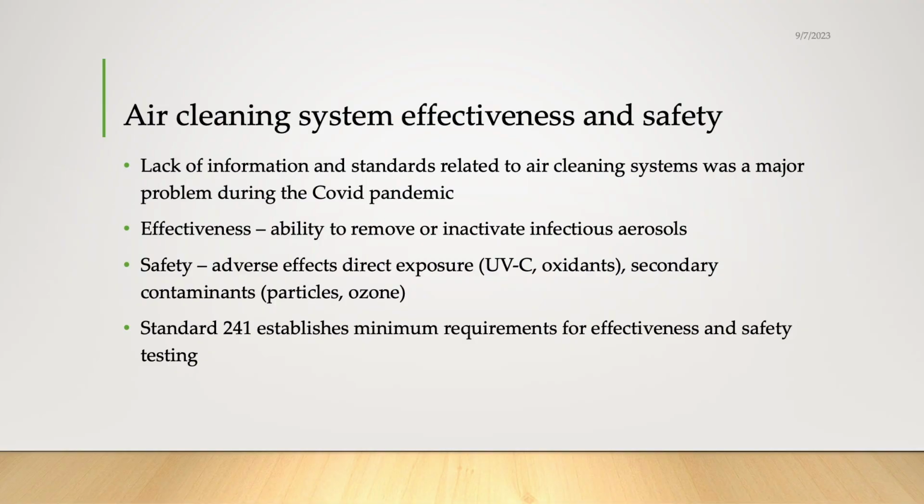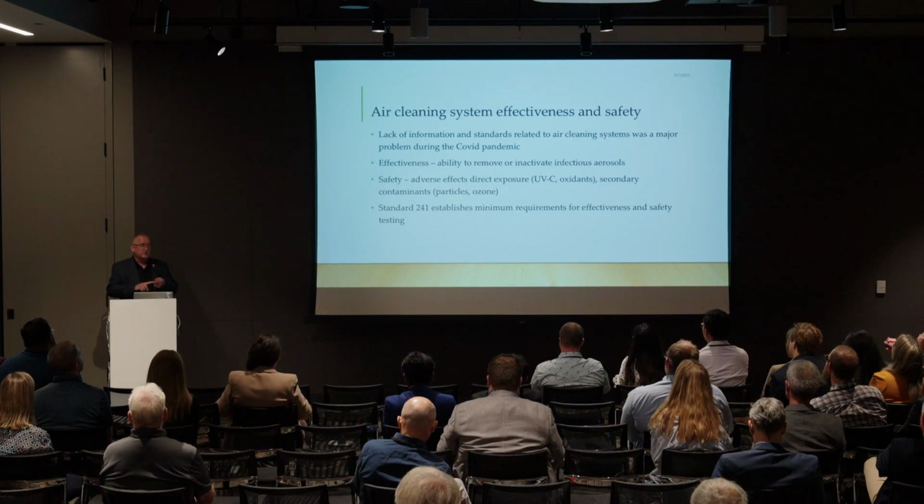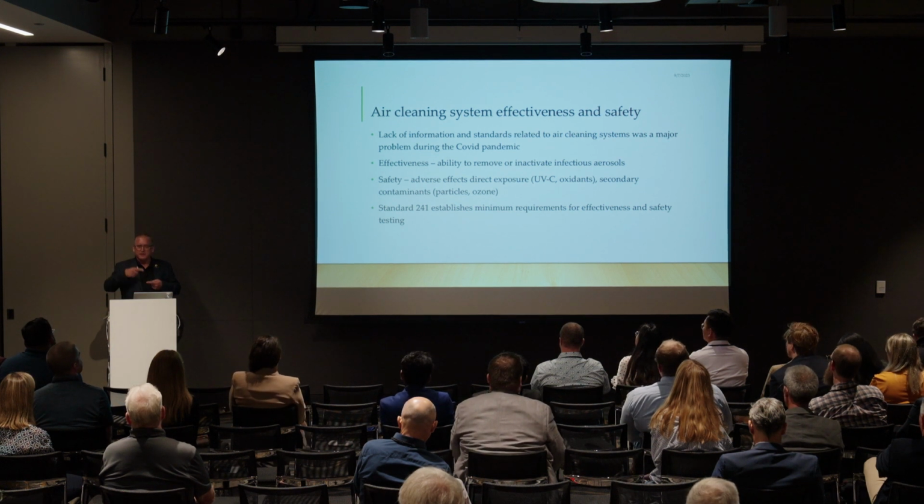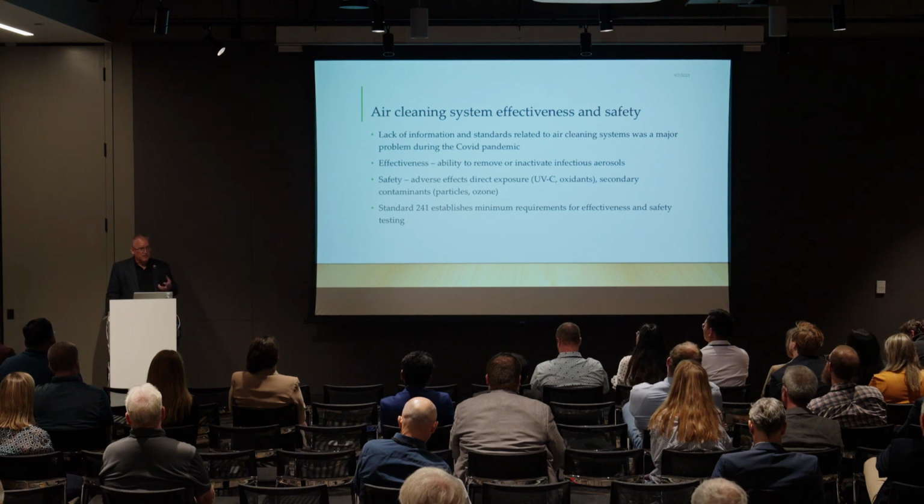The really important piece in the requirements is air cleaning system effectiveness and safety testing. You know, it's appropriate to say at an event called Rodeo that it was kind of the Wild West for air cleaners during the first couple of years of the pandemic, and we wanted to do something about that. We had kind of an information vacuum, so we need to test air cleaners to know what their effectiveness is so we can determine how much they contribute to meeting the equivalent clean air budget, and we also have to know that they're safe. We're well aware that some air cleaners produce secondary contaminants or are contaminants themselves, and we need to limit the amount of them, particularly the oxidants and also to some extent UV. So we've got requirements for both that have never been in standards in the same way.